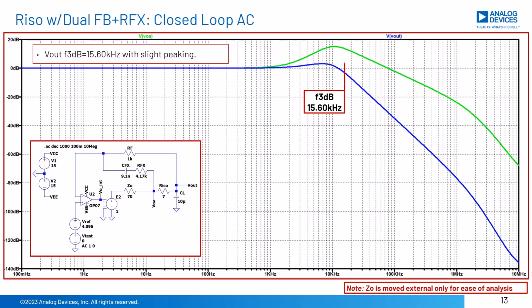The higher frequency pole and zero are known as a pole zero doublet, which will result in gain peaking out of the op-amp at VOA as shown. This is the trade-off of higher frequency correction at CL versus gain peaking. The closer the higher frequency pole and zero are together in frequency, the less the gain peaking will be. This is just the expected response for a pole zero doublet. This will be covered more in an advanced class.